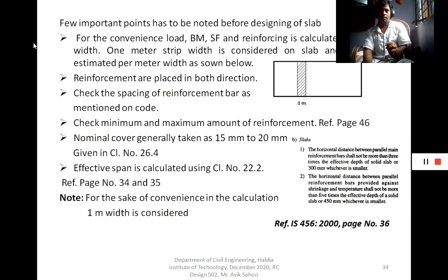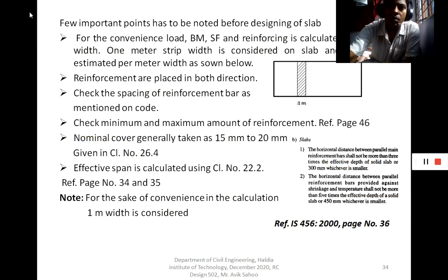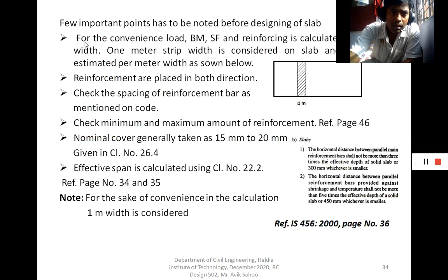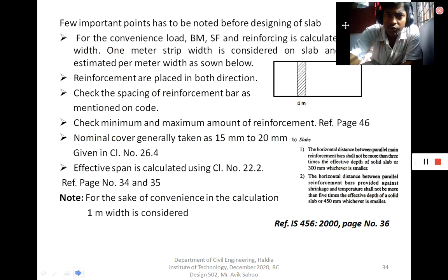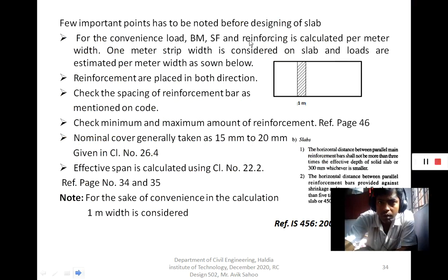Next, when you design a slab, a few points have to be remembered. For convenience, load, bending moment, shear force and reinforcement are calculated per meter width.